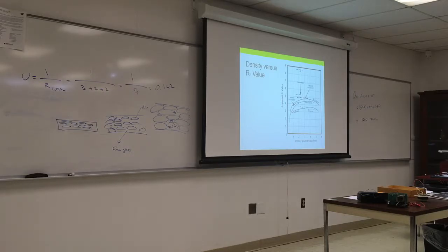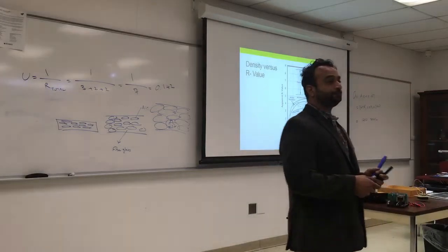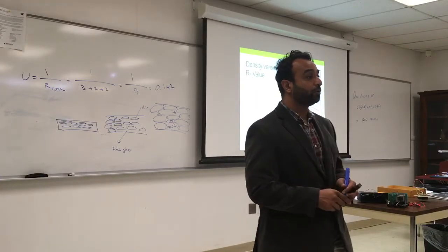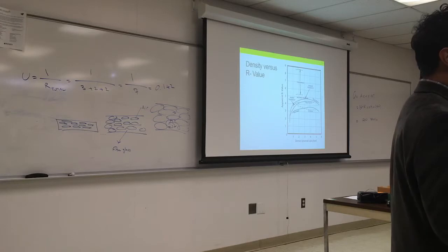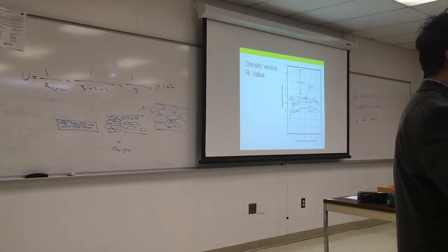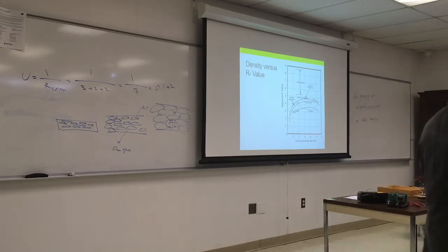And if we were to replace this floor, we need to have some special company come, isolate the area and take them out. So, if you go to old houses and you see some insulation that you cannot identify, be careful, ask around before you start cutting into it, especially around piping, because asbestos was very sticky and it's easy to form and easy to remove.